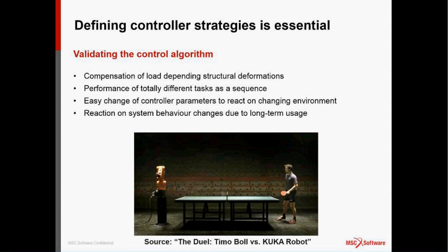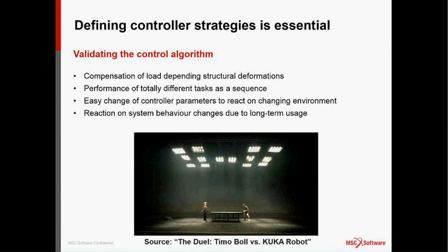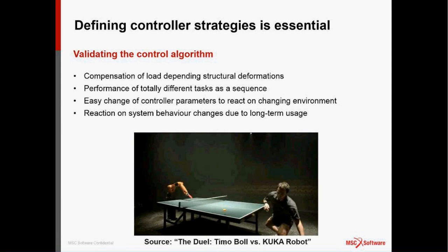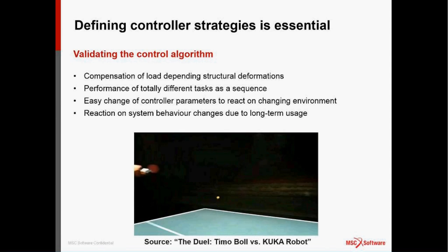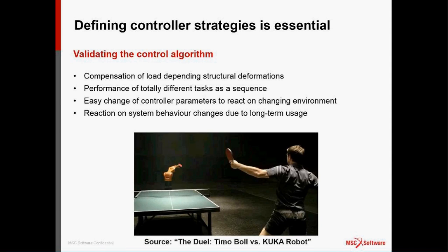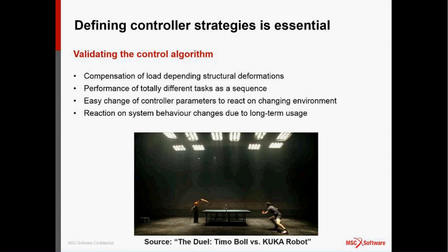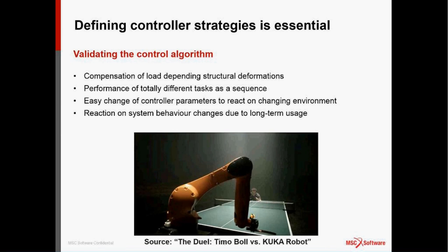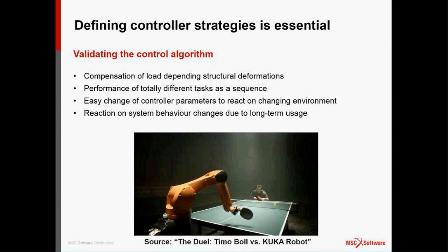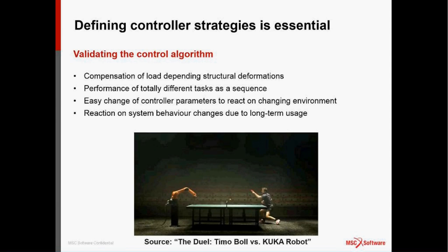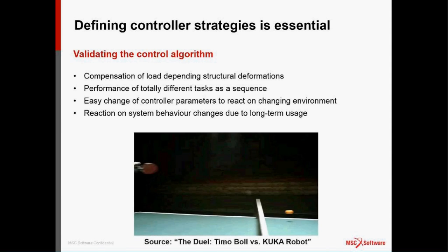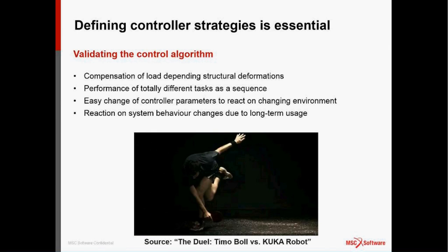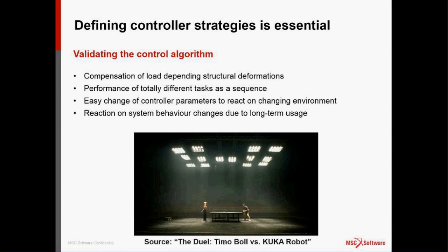But if you really want to validate that with the real physical effects, like how the contact between the different parts is going to affect your final trajectory, or how the structural deformation is going to affect that, then to evaluate your control algorithm with those real physical scenarios taken into consideration, you would need to have a co-simulation between Adams and your control software to help you very accurately validate if this control algorithm is going to work or not.